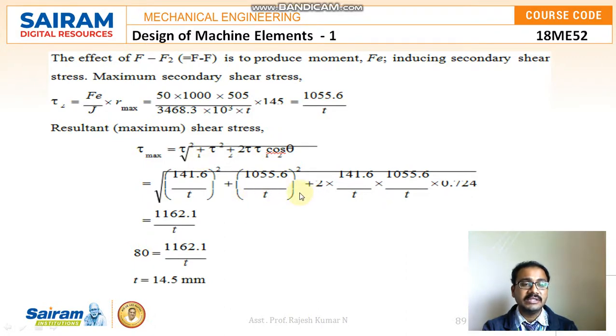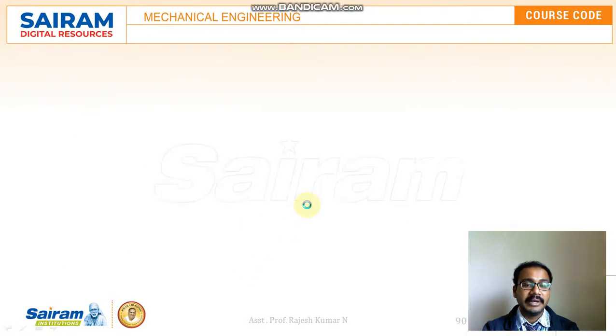By substituting these values, I get tau max as 1162.1 divided by t. Already I know that the allowable shear stress given in the question is 80. By substituting 80 and equating it to 1162.1 divided by t, I get t equal to 14.5 mm. With this the video is completed.